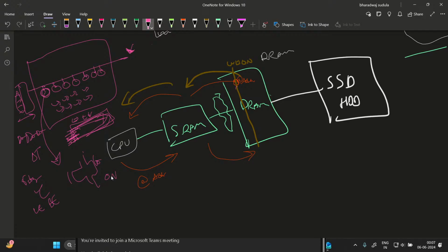It takes some finite amount of time, but very little compared to the row decoding part. So anyhow, we have selected this word line, and instead of taking only this data, we take the entire row and place that in SRAM.